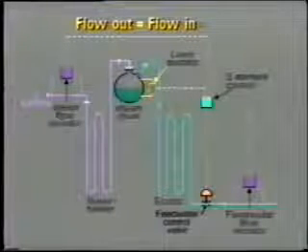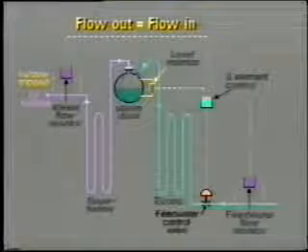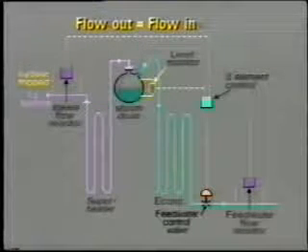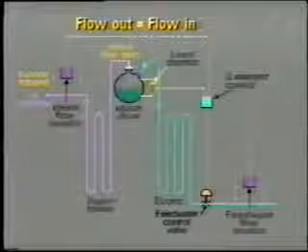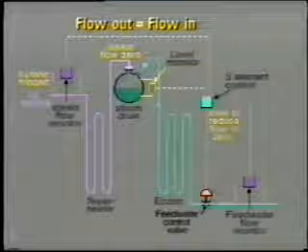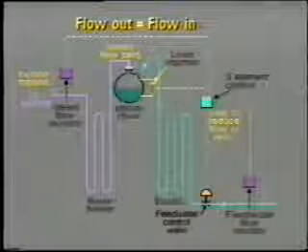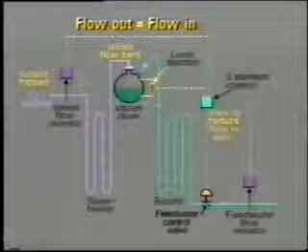For example, let's see what happens if the steam turbine is suddenly tripped due, say, to an electrical fault on the generator. As the steam flow from the HP superheater suddenly falls to zero, the feed water controller would try to close the feed water control valve so as to reduce the feed water flow into the HP section to zero.